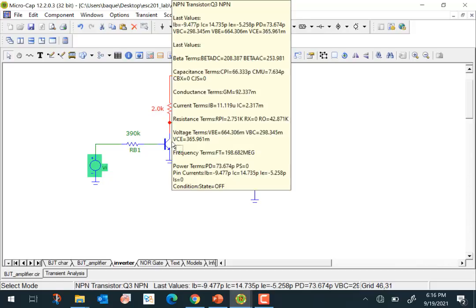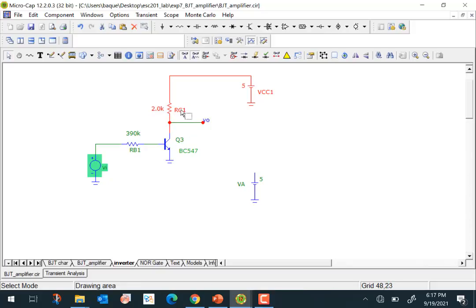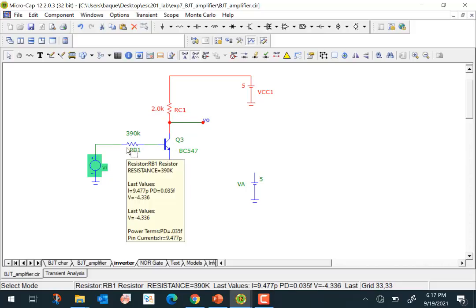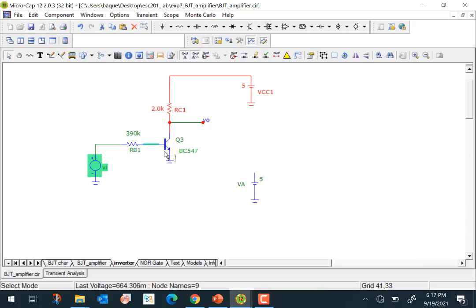Internal transistor capacitances and these resistors play a role, right? Because there's always a charging or discharging time constant. So along with capacitors, the resistors play an important role here. This resistor would be charging up the base emitter capacitance. This resistor would be charging up the capacitances that you see here. So all of those things play a role in determining the speed of the inverter here.